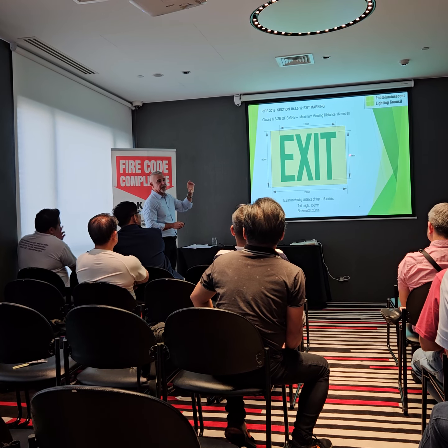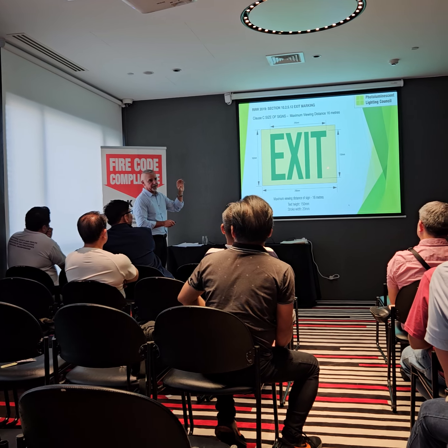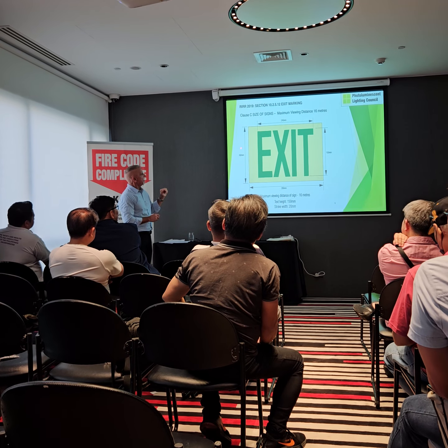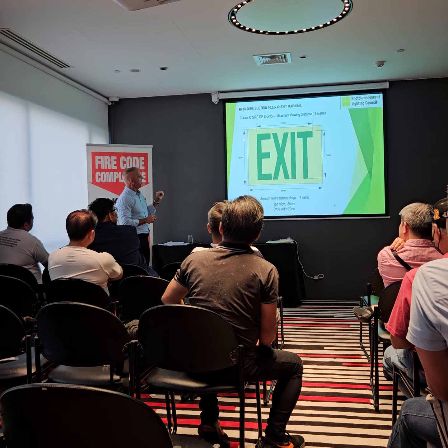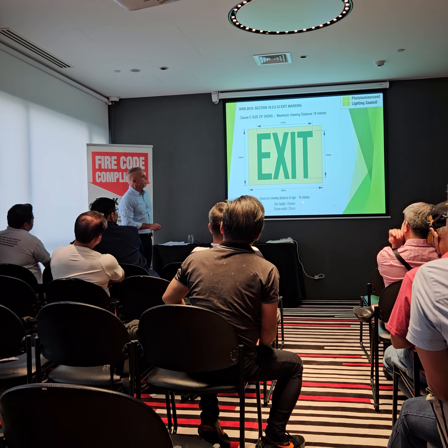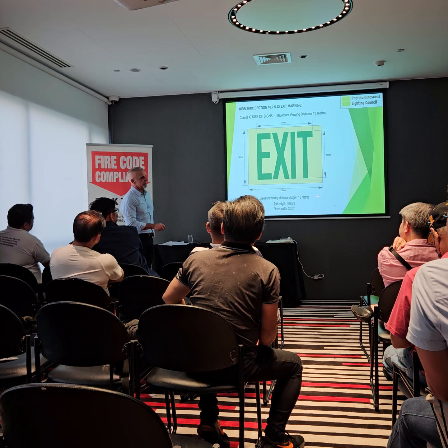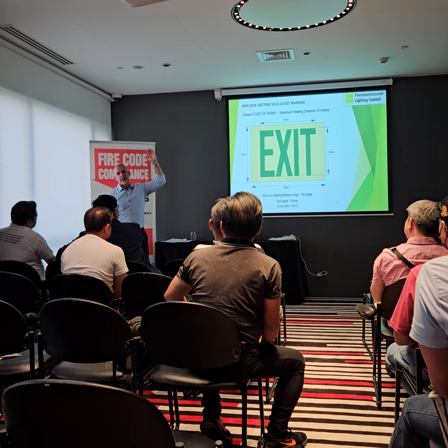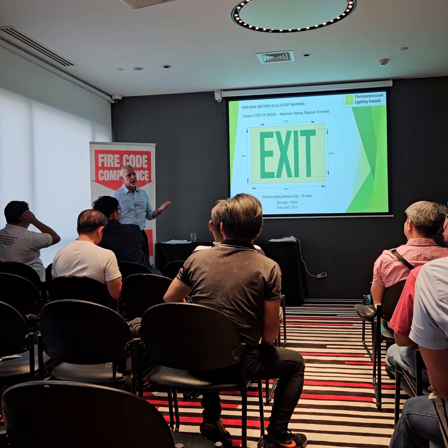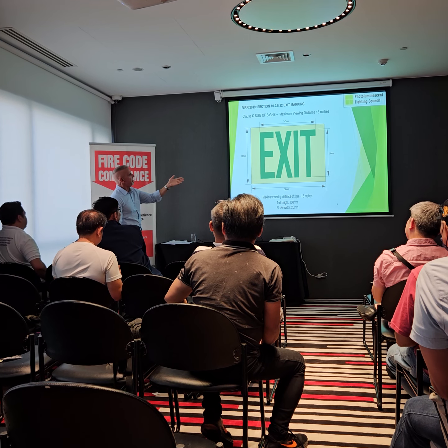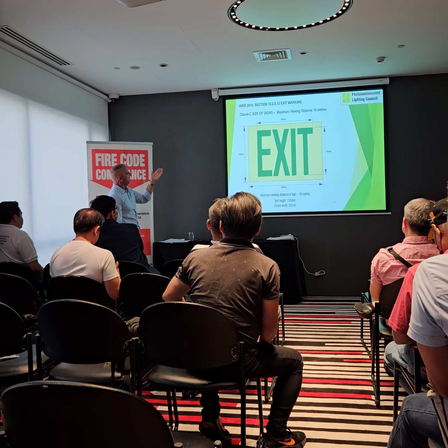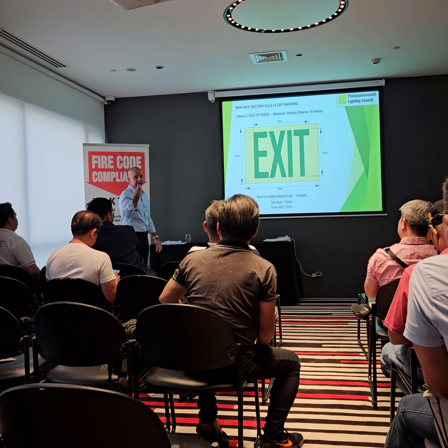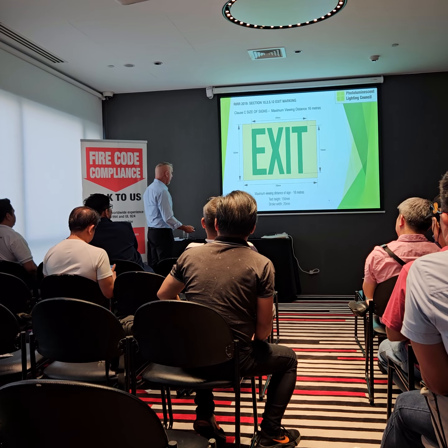so that specifically complies with what it says in the fire code of the Philippines. Luckily, that also fits on a sign that's 162 millimetres high, which means we can take that as a maximum viewing distance of 16 metres. Fundamentally, the bigger the sign, the further you can view it. So 150 millimetres, yep, we've got that, and we can then say, rightio, 16 metres is the maximum viewing distance for that sign.